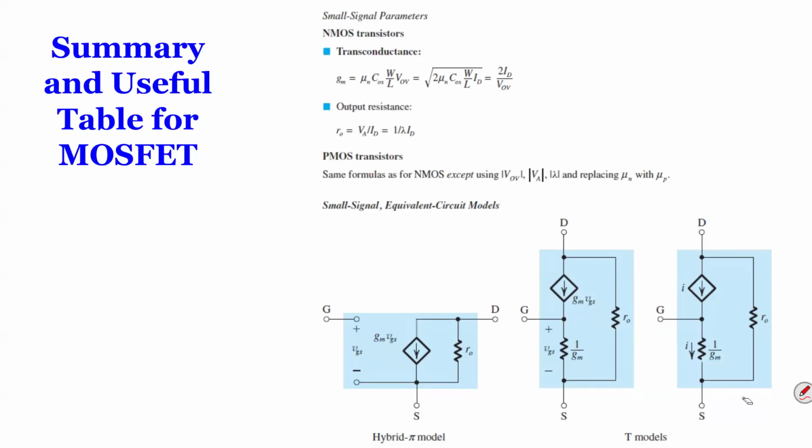Now the last circuit here is just the duplication of this one, but rather than using a voltage VGS as the input, it uses I, right? So you see this becomes I, and this becomes I. This is simple to understand, because if your current coming in here is I, you have the same current coming here because there's no current at the gate.